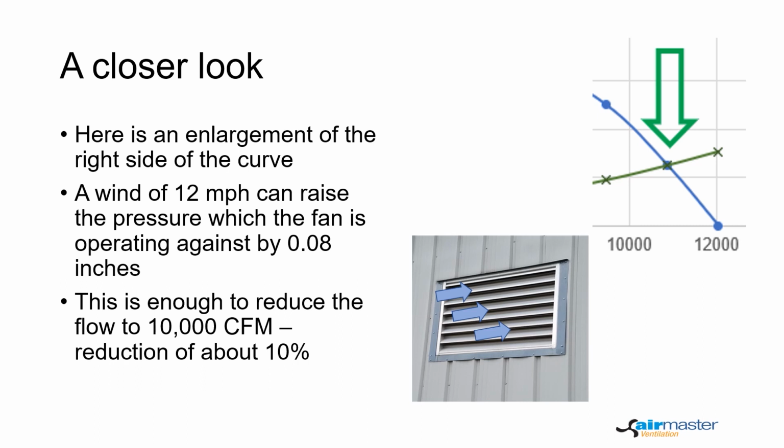So the wind has reduced the flow by almost 10%. So it just goes to show it really does depend on which way the wind is blowing. Moral: if flow is critical in your application, provide plenty of margin for upset conditions. But more important, this shows another aspect of having a difficult time in determining fan flow.